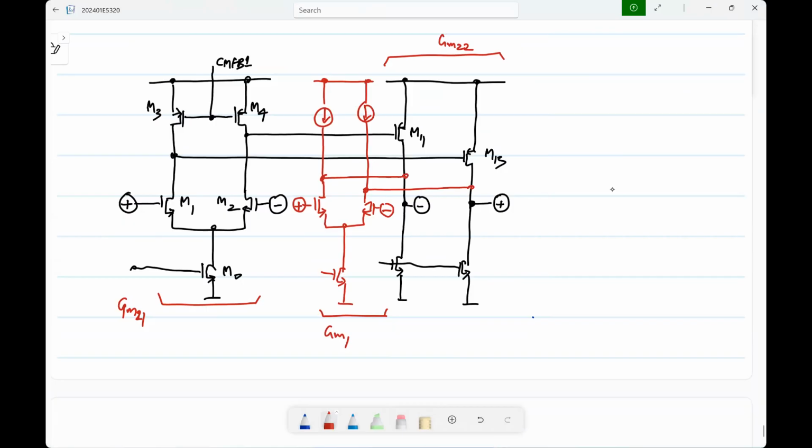So essentially all you have done is like GM1, another differential pair in parallel. So what disadvantage do you see here? Do you see any? We had the two-stage Miller op-amp. Compared to that, does this introduce any disadvantages? What might that be?